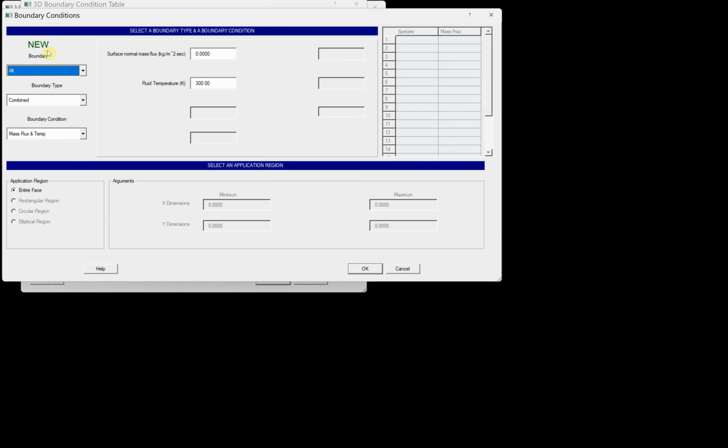And it also has a 0 flow boundary on all the boundaries. And that's okay. What we're going to do is modify it. Actually, let's go in and modify this one to be hydrostatic pressure everywhere. And we have to give it a temperature in case there's inflow.